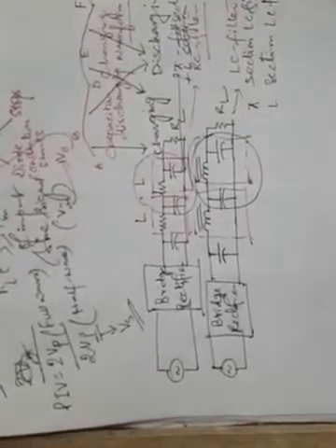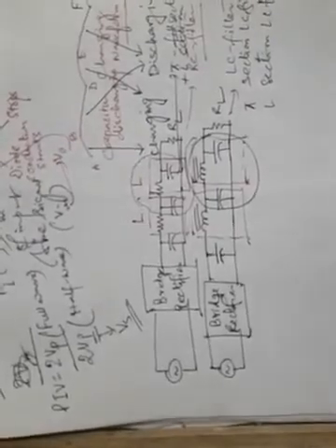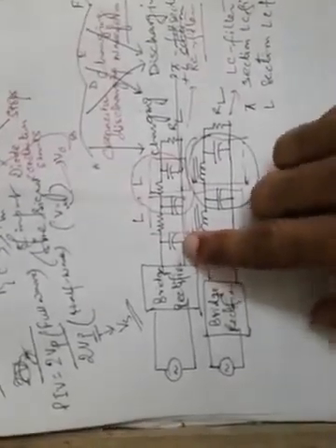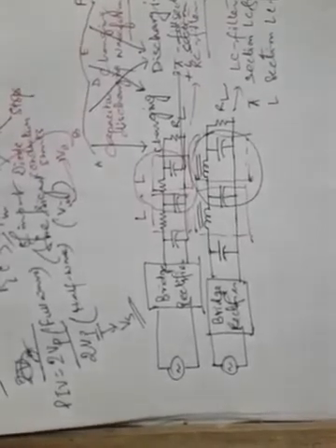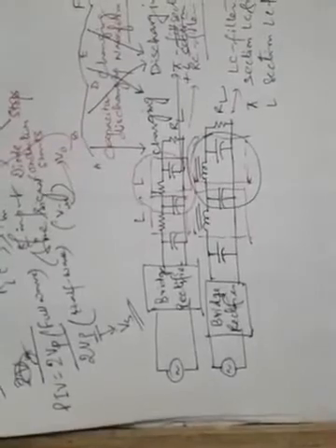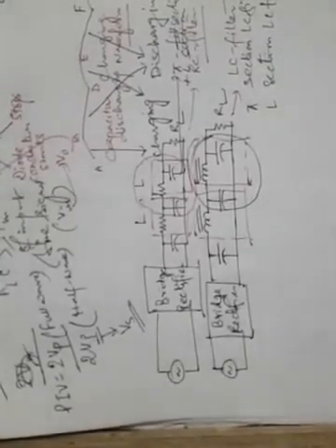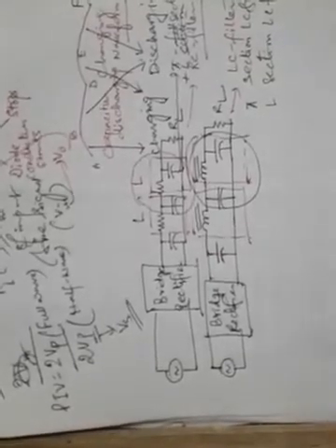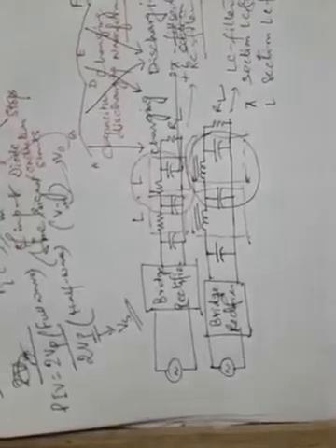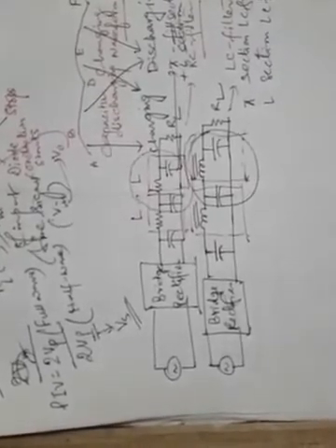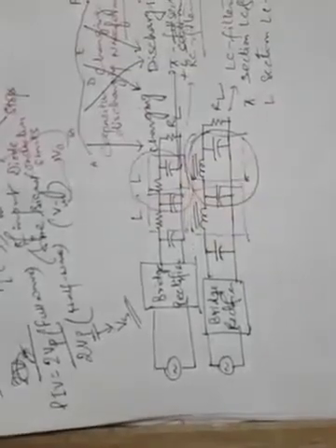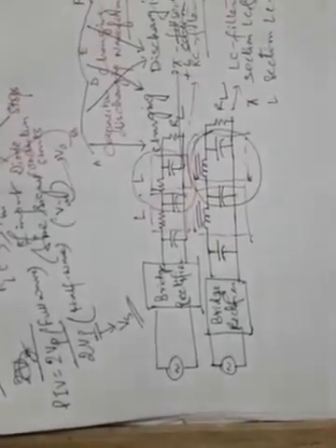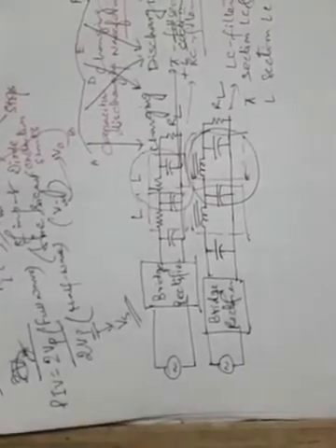the designer who will design this circuit will settle for a peak to peak ripple of as much as 10% across the filter capacitor if only a single shunt capacitor filter is being used. The reason for not trying to get even lower ripple is that the filter capacitor would become too large. To get the ripples to reduce further, the filter capacitor would become larger. Additional filtering is then required, that is done with the series cascading of two L section RC filters, or we can say a pi section RC filter between the filter capacitor and the load resistor.